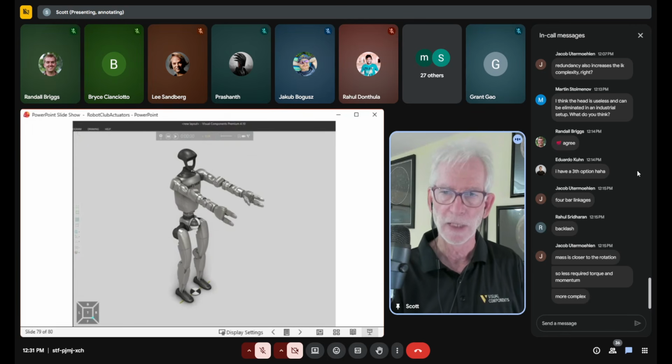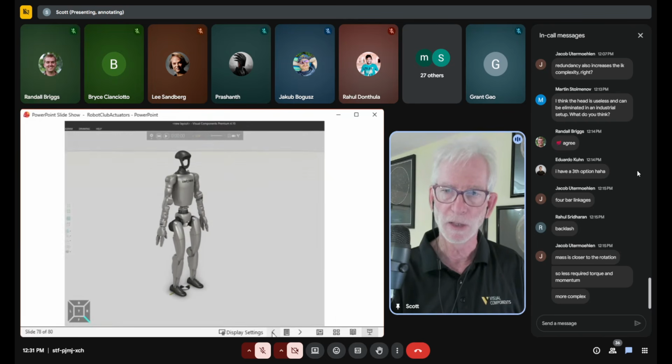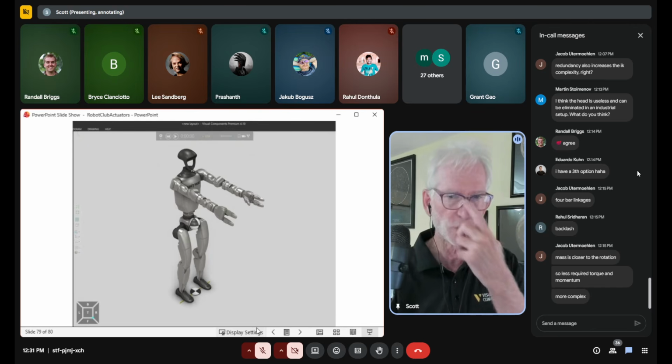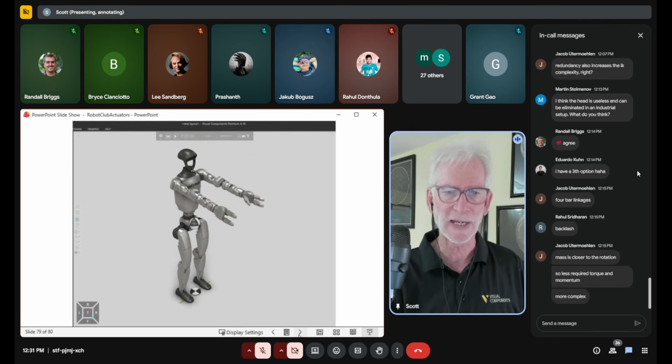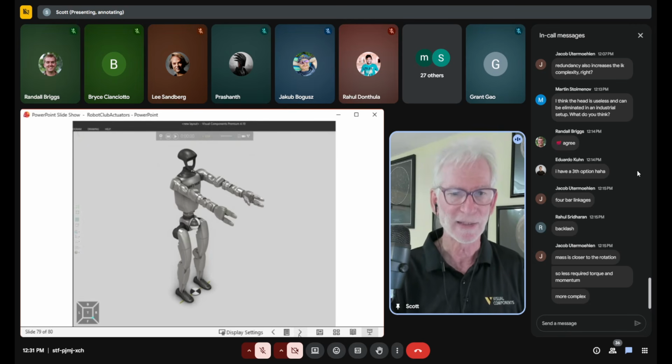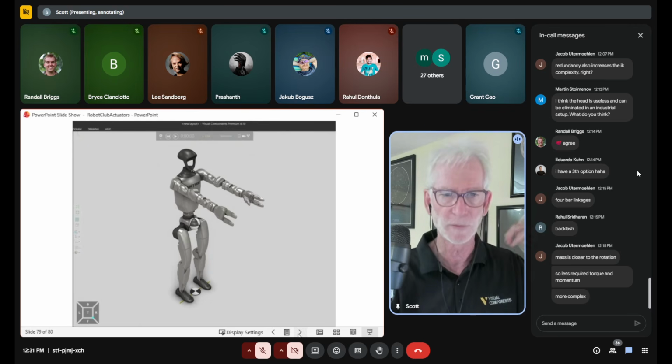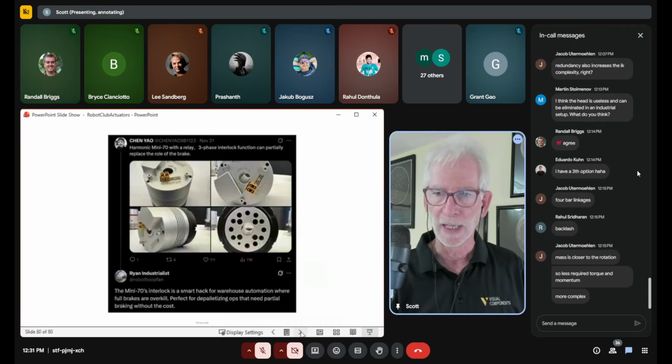So when you put that out there, as you can see, the center of gravity here moves. You see that little ball, you can barely see it here. When the arm goes out, suddenly the center of gravity has shifted a little bit, and you can see the center of pressure down on the ground, which we want to keep between the heel and the toe. If it goes too far forward, we're going to lose balance and fall over. So you can go through this exercise, and because it's an XML sheet, you can read it and almost figure it out yourself, as well as use a very simple XML reader in a Python script to suck the data in if you want that.